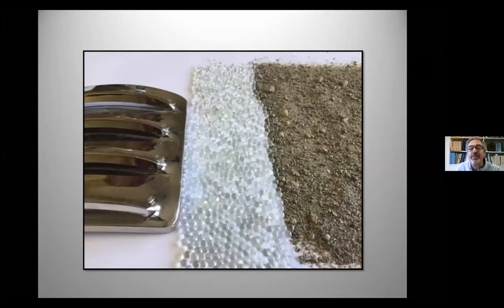So for example, you remember that previous slide, that formation was relatively uniform. We have seen occasions where that very fine sand will run right through the regular spaced interstitial spaces between the beads and make it through the screen.